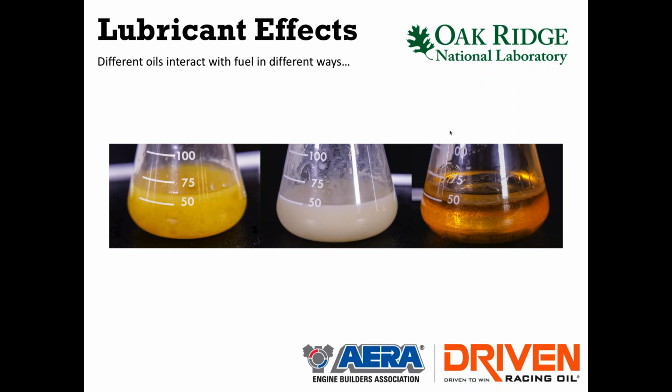And there's a big part there, because when the oil and the fuel mix, bad things can happen. You really want the fuel to be the fuel and the oil to be the oil. What we see here is combining 3 different oils with a given amount of fuel. You can see that the one on the very far left has separate droplets of fuel within the oil, but still in bulk there's a mixing, a homogenization, if you will, of the oil and the fuel, while there's still some fuel held separate.